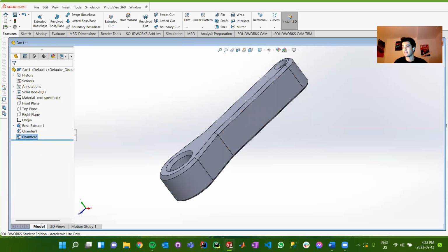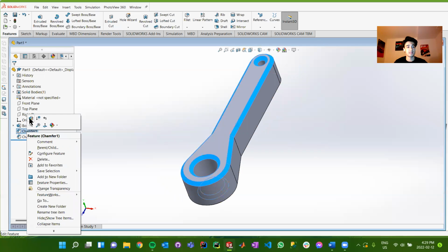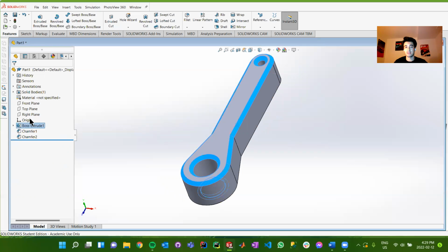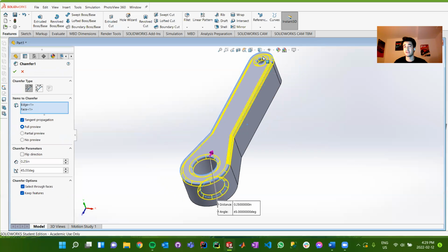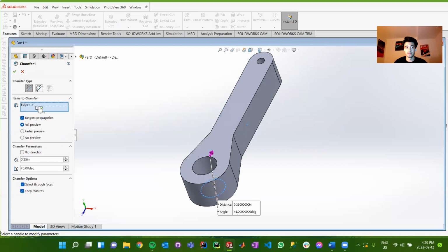I realized that these two armholes that we have on the end here should not have been chamfered. So I'm actually going to get rid of those. I'm talking about these guys. So let's go back, because it's going to be a very weird countersink. Okay. And instead of choosing the face, what we'll do is we'll actually choose the edges.